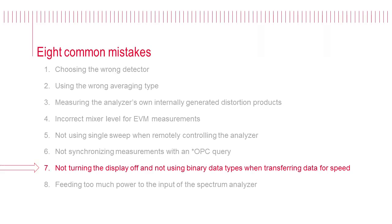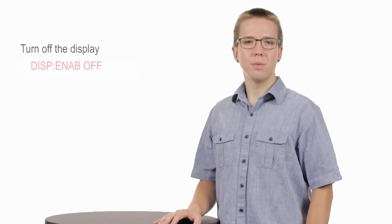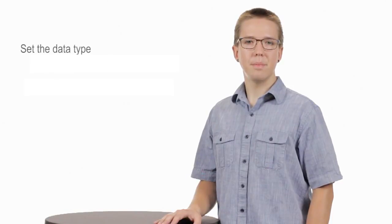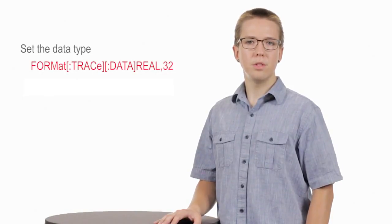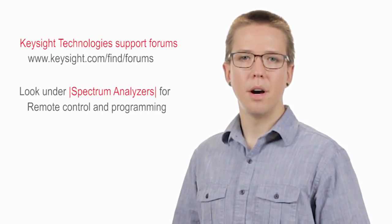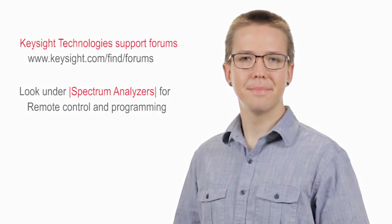The seventh mistake occurs when transferring data. Not turning off the display or using binary data types can slow down your automated measurements. To maximize test throughput, disable the instrument display using display enable off. Use binary data to reduce the amount of transferred information. To set the data type, use real32 for 32-bit binary data, or for 64-bit, use real64. For more help with automating your measurements, check out the Keysight support forum on remote control and programming.